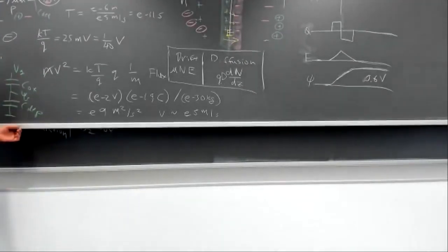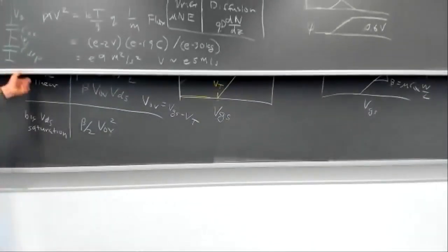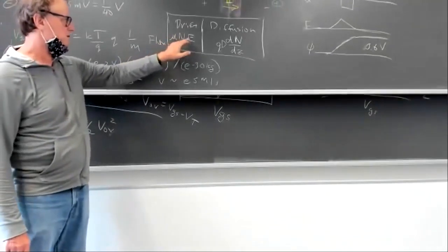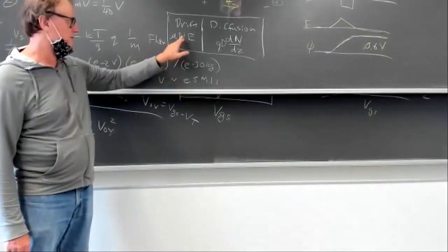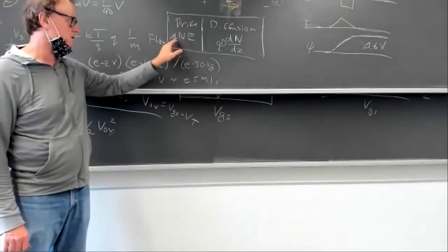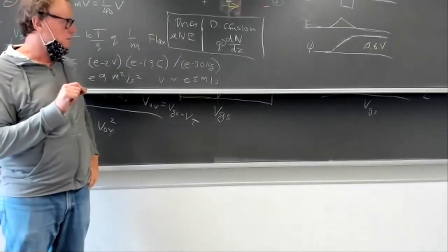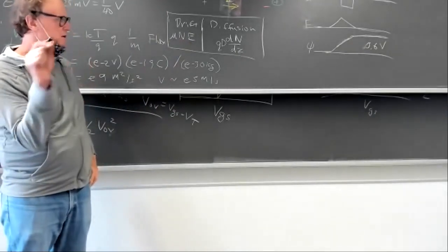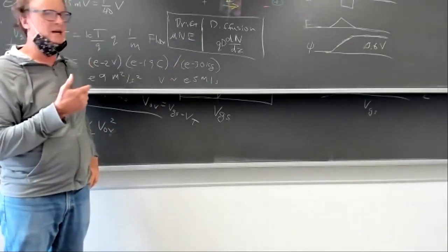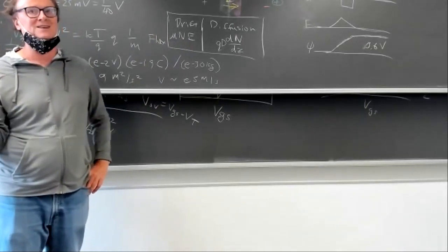Yeah, in reality, the drift current, I've written it like this, that the drift current is proportional to this electric field and a constant mobility. It's not true. For a very large electric field, it's not linear anymore because the carriers get accelerated a lot between collisions, and eventually there's so-called saturation velocity. No matter how big an electric field you put on, it doesn't go faster, right?